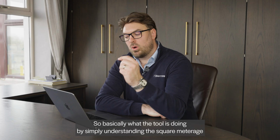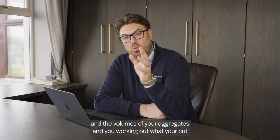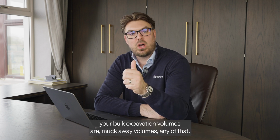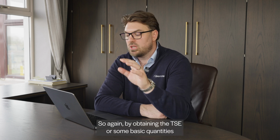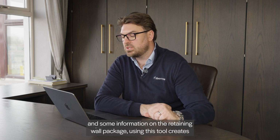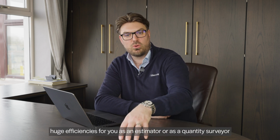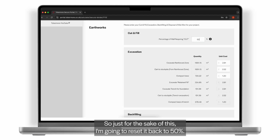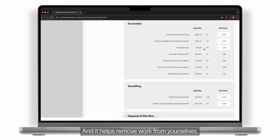So basically, what the tool is doing by simply understanding the square meterage and the volumes of your aggregates, and you working out what your cut and fill percentage is, you now don't have to worry about what your bulk excavation volumes are, muck away volumes, any of that. The tool has taken care of all of that for you. So again, by obtaining the TSE or some basic quantities and some information on the retaining wall package, using this tool creates huge efficiencies for you as an estimator or as a quantity surveyor pricing up these retaining wall packages. So just for the sake of this, I'm going to reset it back to 50%. So that's what our cut and fill percentage does, and it helps remove work from yourselves.